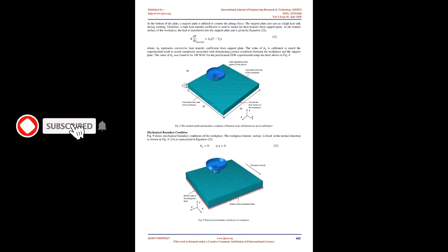Time steps and the boundary conditions used in the modeling are listed in Table 2. The Pintool had a plunge rate of 0.4 mm/s and plunging occurs for 15.2 seconds. More detail on the current FSW model can be found in our previously published work 25. Where, the symbols denote the user-defined factor, the deviatoric stress, the rate of plastic straining, and F, the plastic energy dissipation energy. In the present work, 90% of frictional and plastic energy is assumed transformed into heat energy 3.